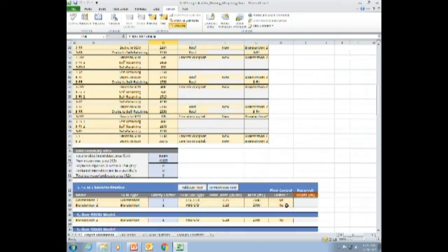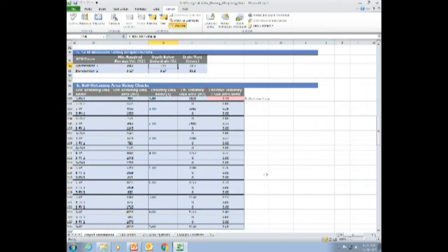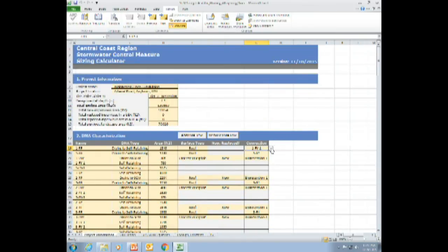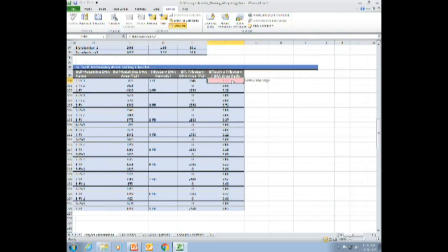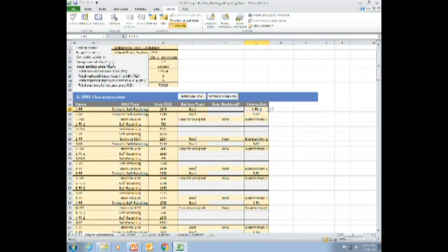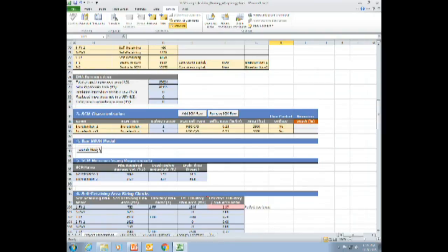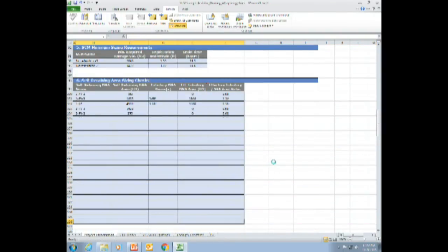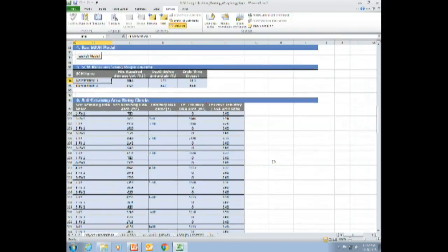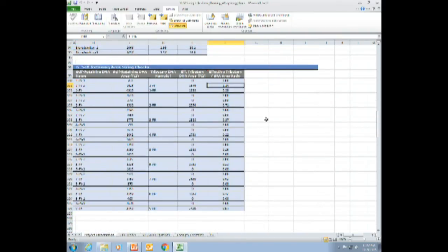All right. However, the front of the yard, DMA 1 FY1, is only 780 square feet. Our ratio of contributing impervious to the size of the self-retaining area is too big. Note, color-coded, right? Ratio is too large. Instead, let's drain it to the other part of the front yard. There we go. We're okay.